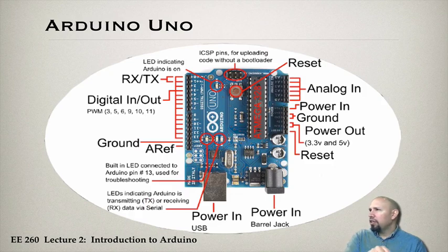So we have some other things that are going on. In addition, part of what this Arduino can do is communication. The ICSP pins can be used for communication. Also, some of these digital pins, pin 0 and pin 1, can be used to do receiving and transmitting of data. So it's built in that way, and there are functions that just access those pins directly to do some communication.